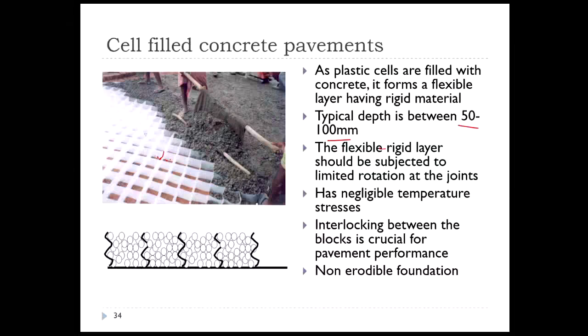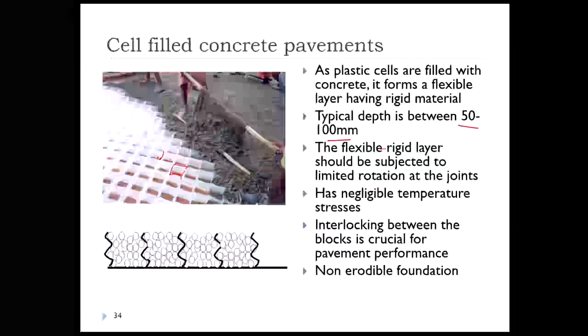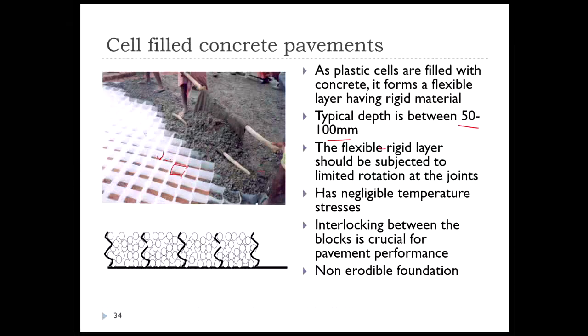Now, since slab dimensions are very small, you have negligible temperature stresses here. Interlocking between the blocks is very crucial for performance. This has to be placed above a non-erodible compacted foundation.